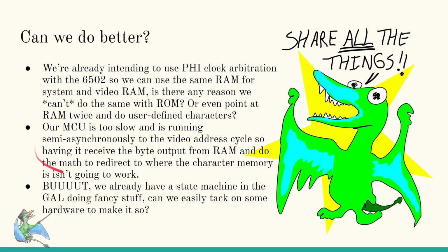So, as I mentioned earlier, one method that someone would probably use with a faster microcontroller, or you could program this into an FPGA, would be, when you got the first address, to take the byte of memory that comes out, read it into the MCU, and then add it to some offset, and then run a second cycle by putting it on those address lines that we've already got buffered, and have that one go straight to the shift register.